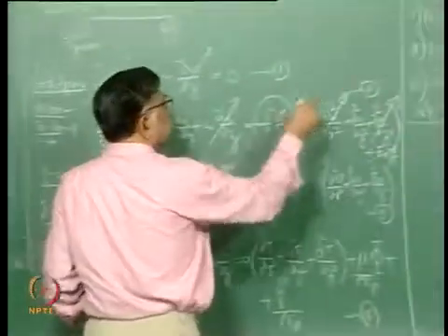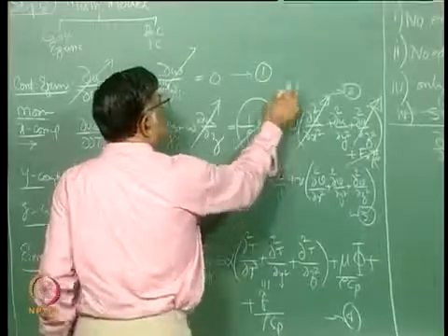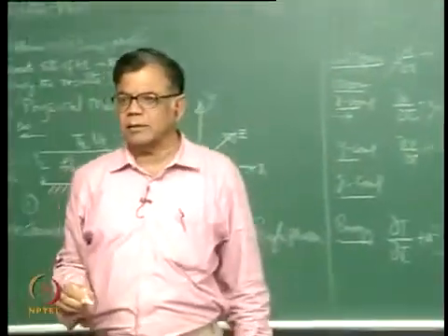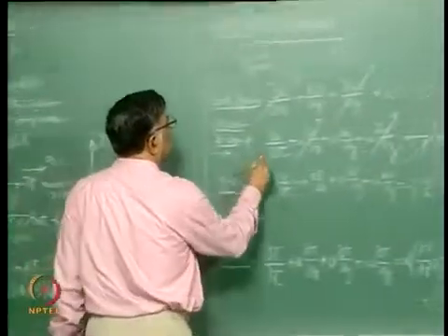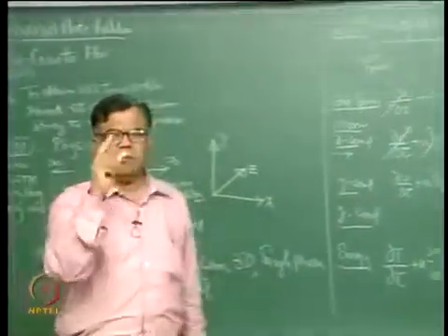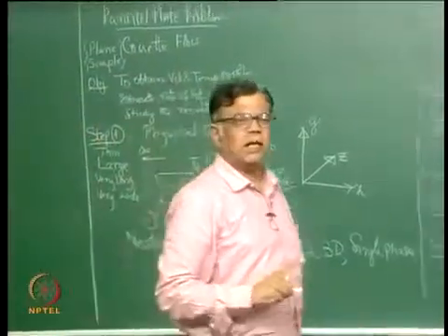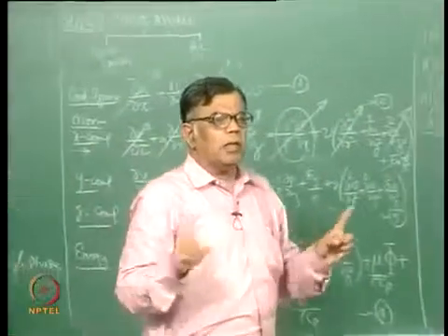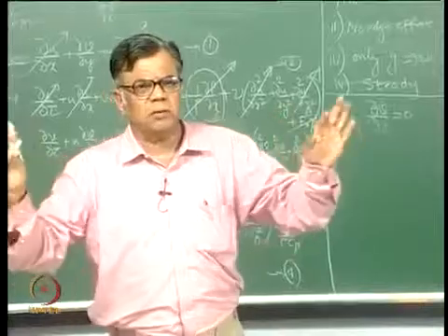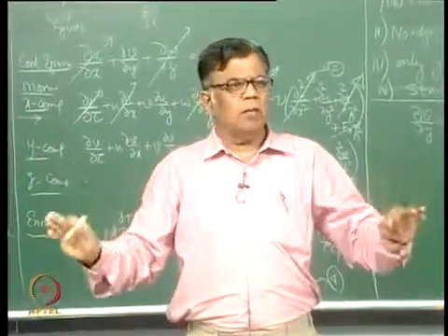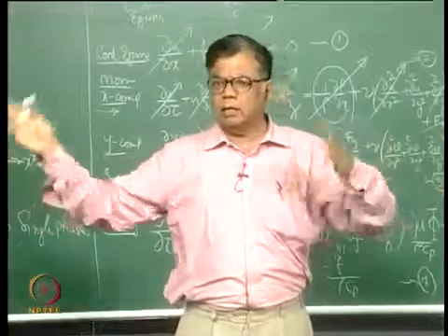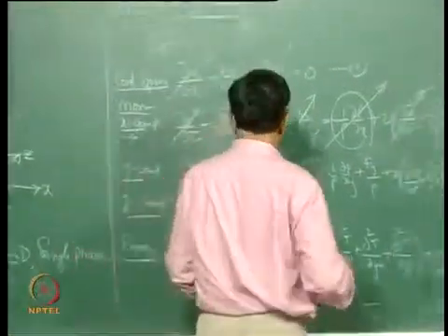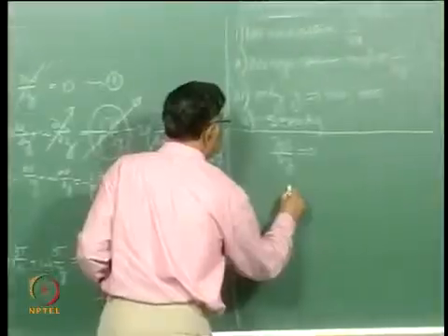So also we are saying no edge effect, so all del by del x is cancelled. So steady state. Now write down the expression. What is the x component momentum? There are no boundary layer assumptions. This is the Navier-Stokes equations with certain geometry, flow and some assumptions we have made, like no end effect, no edge effect. So what is this?